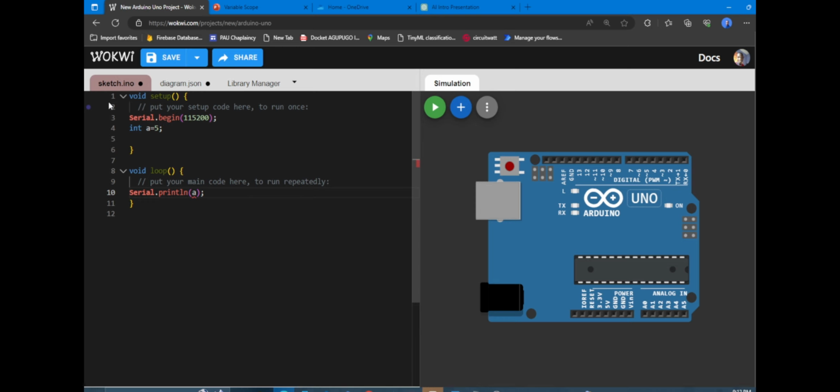So you are done with lines 1 to 6. Now we're in the void setup, which is from 8 to 10. Now we're in the void loop, which is from 8 to 11. We continue looping, and there's no a in it because a has been destroyed after the code came out of void setup. So a is no longer useful in the loop. And since Arduino keeps going inside the void loop, when you run the void loop, it goes back to the beginning of the void loop and keeps running. So a is practically useless after I come out of the void setup. So that's a local variable.